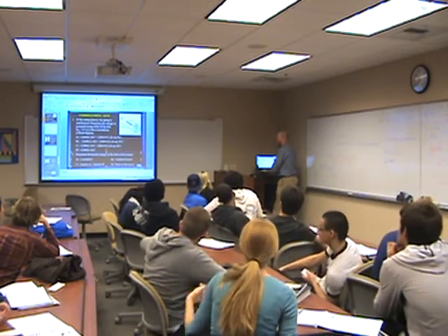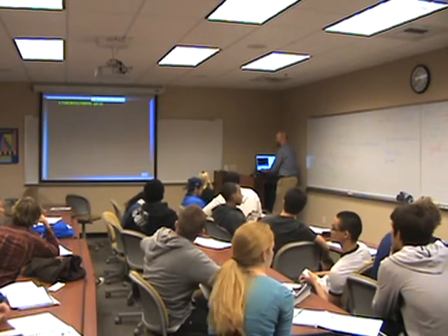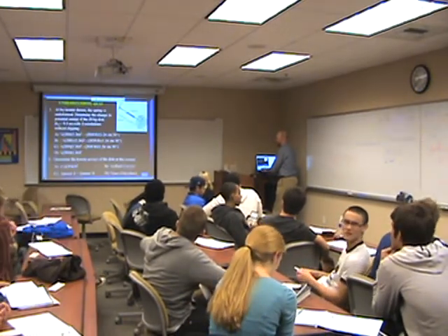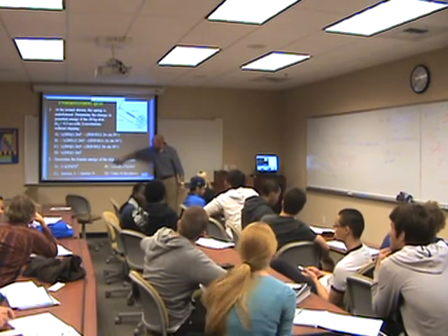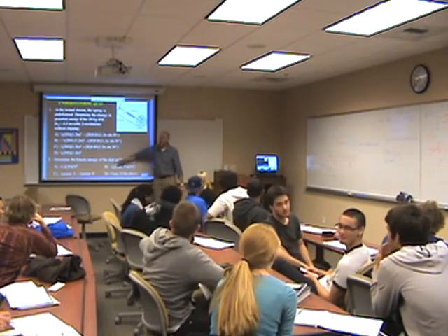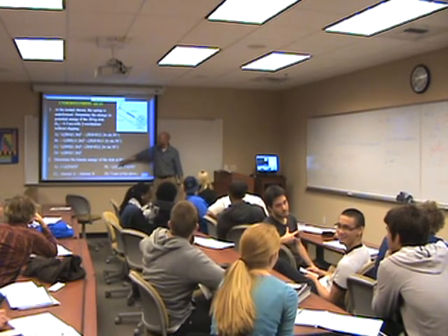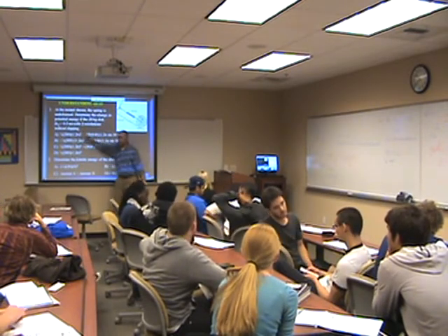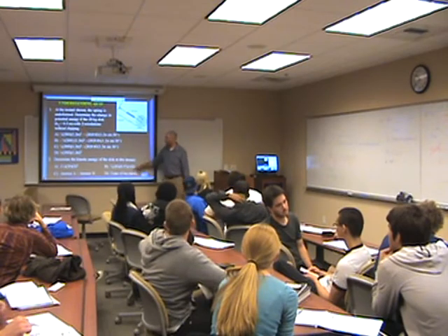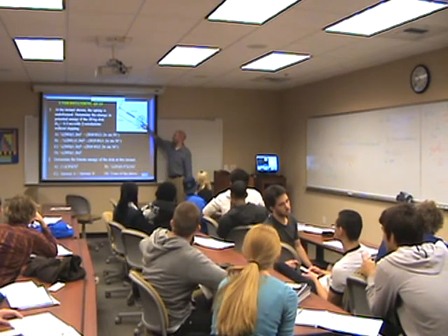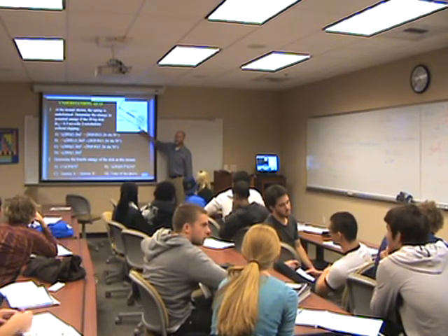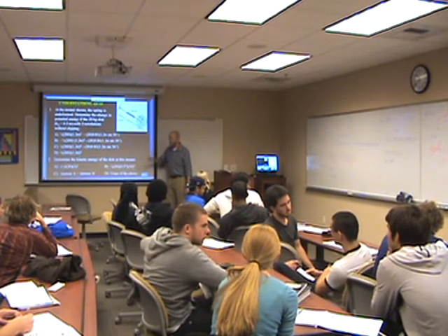One more time. This is the radius of gyration. This 1/2 is I_G because kG is 0.5. And the 10, how do we get 10? It's V over R. It's omega. V over R is 10.